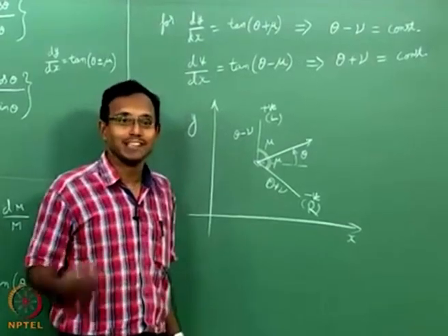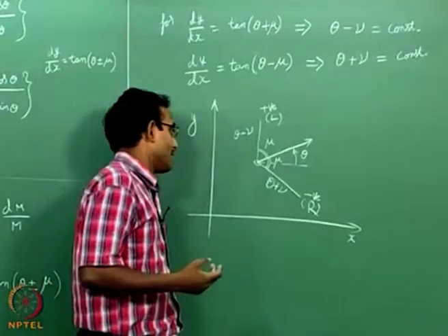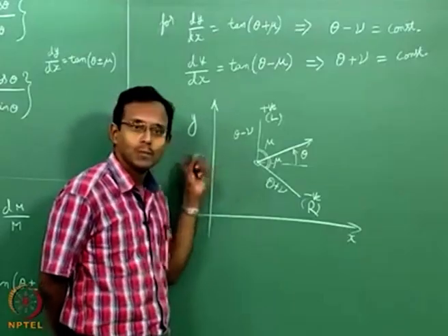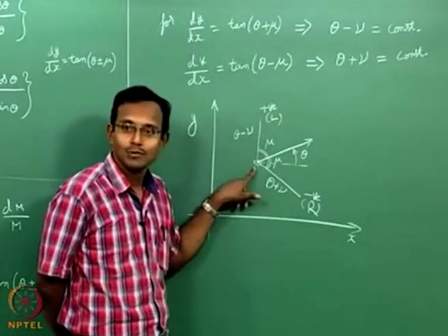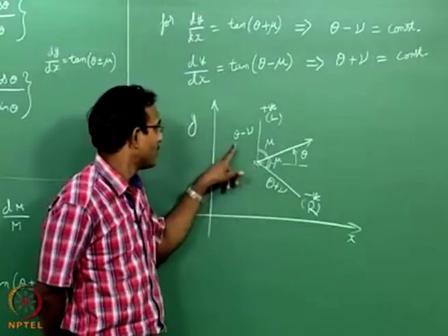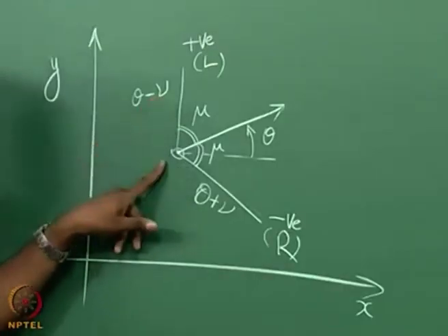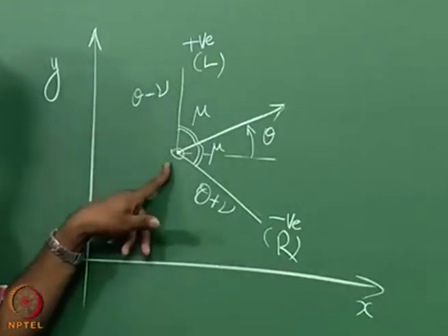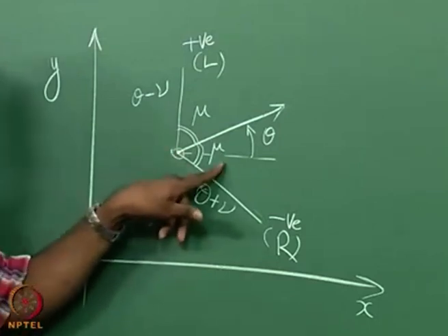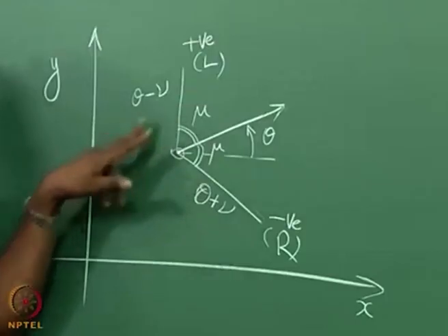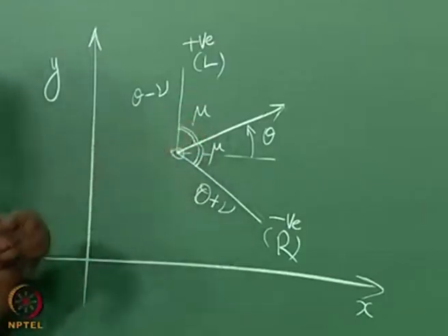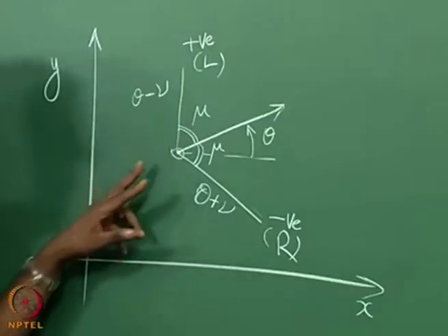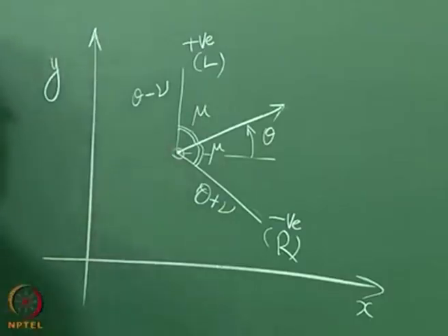Ideally in gas dynamics typically it is 2. Okay? But we got this thing, where are those two constants, two numbers that specifically talk about this point? I can think about theta and nu probably at this point. That is one way of looking at it. Typically people use theta and Mach number, because once I get Mach number I can get this mu easily. Of course I have nu, from there I can get Mach number and get mu also. Typically people store theta and Mach number at every point. Okay. That is how typically people work with in method of characteristics.